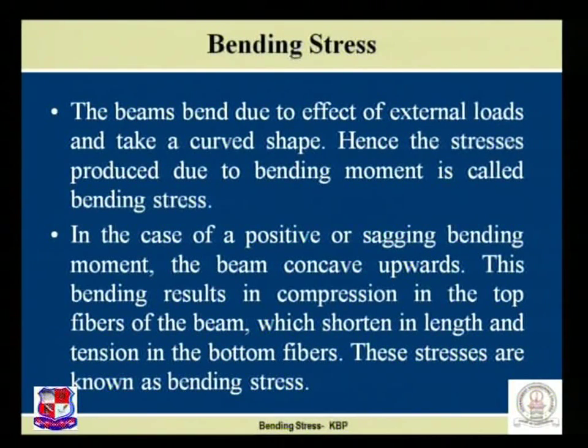In the case of a positive or sagging bending moment, the beam is concave upward. This bending results in compression in the top fibers of the beam, which shorten in length, and tension in the bottom fibers. These stresses are known as bending stresses.